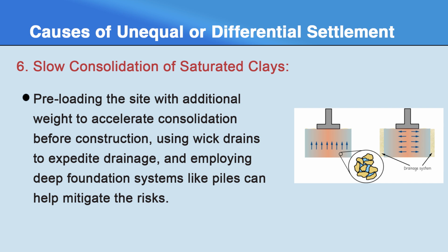Preloading the site with additional weight to accelerate consolidation before construction, using wick drains to expedite drainage, and employing deep foundation systems like piles can help mitigate the risk.